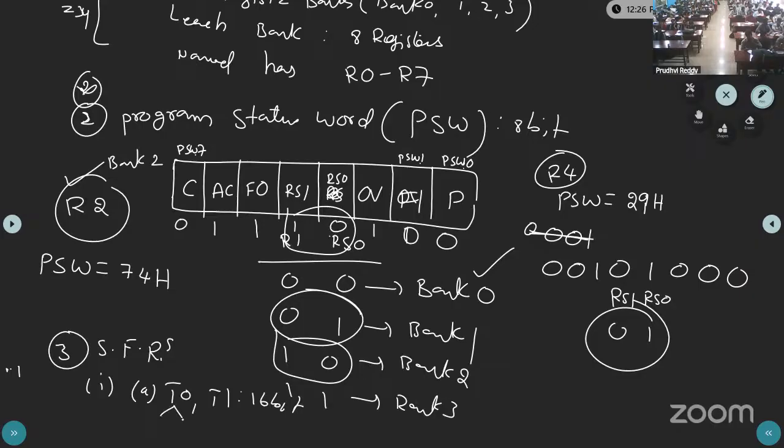This can also be used as TH0 TL0 and TH1 TL1. T0 and T1 are complete 16-bit registers that you can use directly, but we can also use them as 8-bit registers. T0 we divide into TH0 TL0, and T1 into TH1 TL1. A is over.